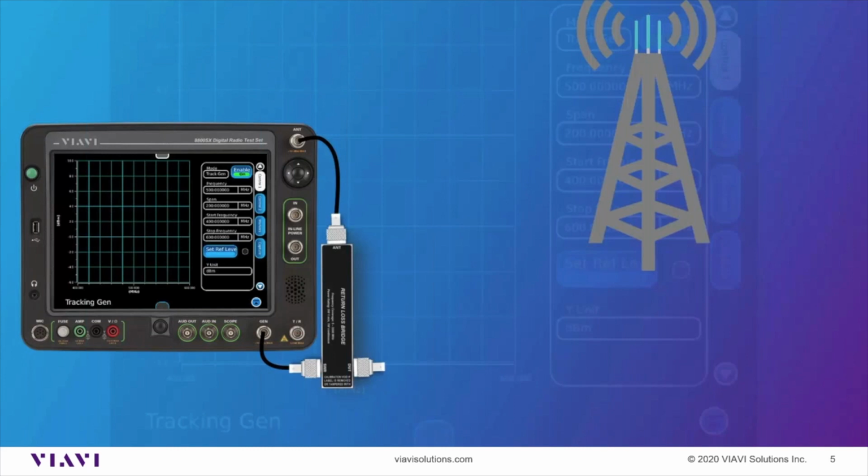As far as distance to fault goes, it's really a frequency domain reflection. That's a technique that we use to do the distance to fault, which is abbreviated as DTF. We feed a swept frequency signal into the transmission line, and our receiver measures the interference pattern generated when our swept RF output signal adds and subtracts with the reflected signals from the faults and the other reflective characteristics within the transmission line.